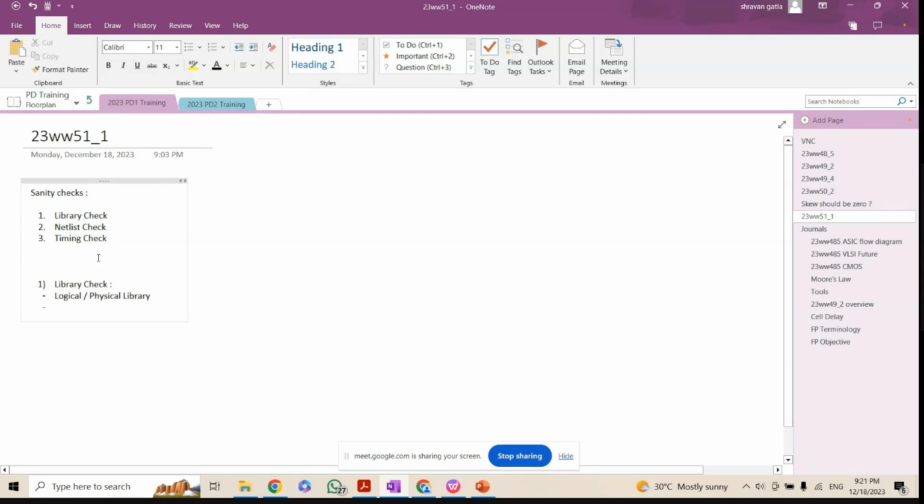We will check if it can be fixed by rerouting. We will open our routing database, the final DB, and see which paths are not meeting. Let's say that a path is routed very badly in lower metal layers, maybe M1, M3. Lower metal layers give high delays, the RC delays, resistance and capacitance. A net is nothing but the combination of resistance and capacitance. So the RC delay is high.